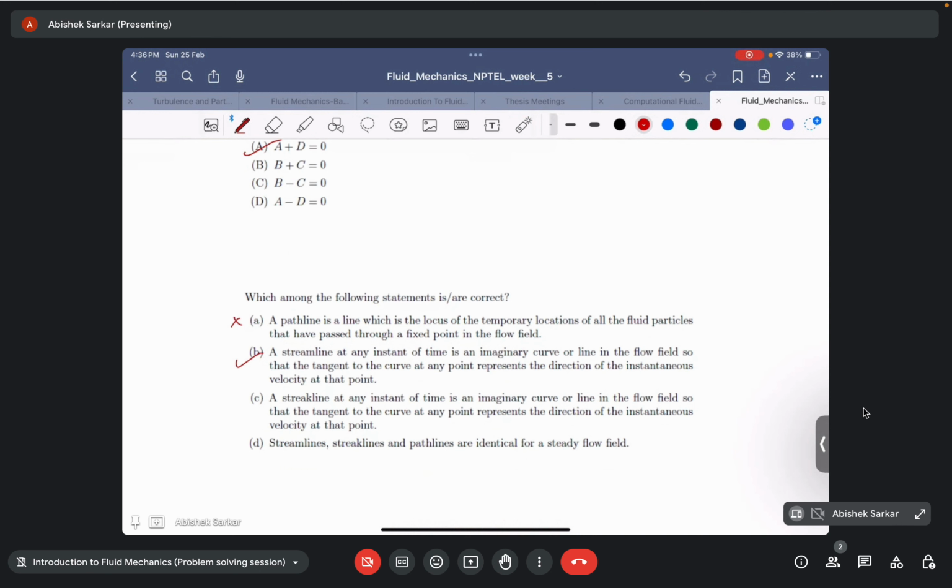Option C is, a streak line at any instant of time is an imaginary curve in the flow field so that the tangent to the curve at any point represents the direction of the instantaneous velocity at that point. So this is basically the definition of streamline. So this is not correct because it is not a streak line, right? And finally, option D is, streamlines, streak lines and path lines are identical for steady flow. I guess we discussed it and how this statement is very important and how it helps us in flow visualization. So this statement is correct. Okay.